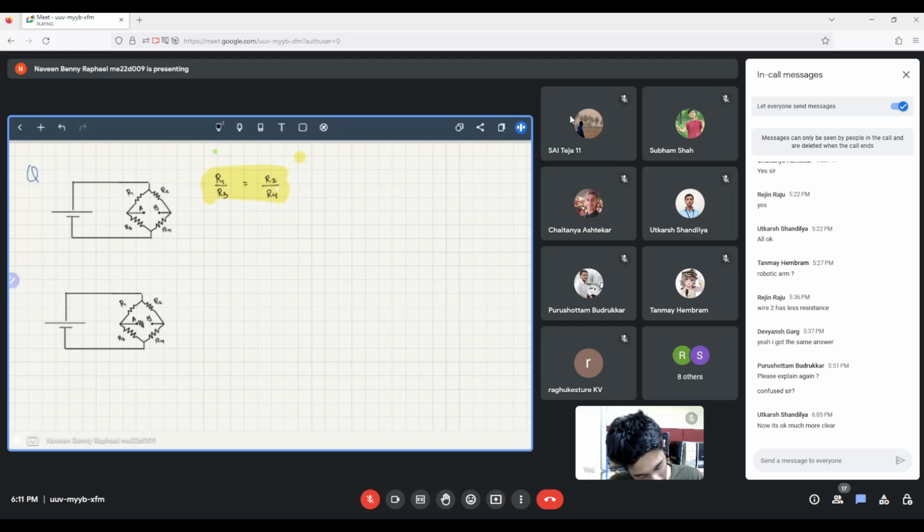Say I have a resistor here. According to the Wheatstone principle, as long as this condition is satisfied, there is no current across the resistor R5. Note that you cannot place another voltage source here and expect the equations to be the same, because naturally it won't be the same. This is a different system altogether. But we can analyze this in terms of Thevenin equivalent circuits. So first, let's find the Thevenin equivalent resistor.